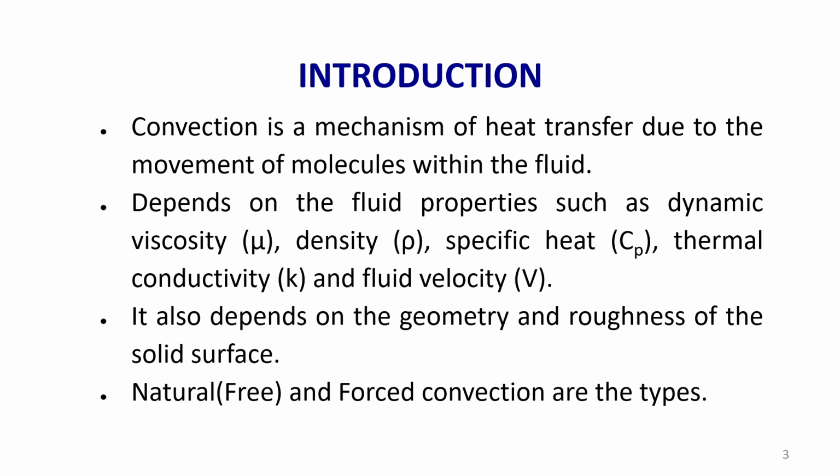It is between a solid surface and a fluid. The fluid can be gas or liquid. Both conduction and convection require a medium for the heat transfer to take place. Of course, in both cases there should be a temperature difference, the driving force. If there is no driving force, then there cannot be heat flow.